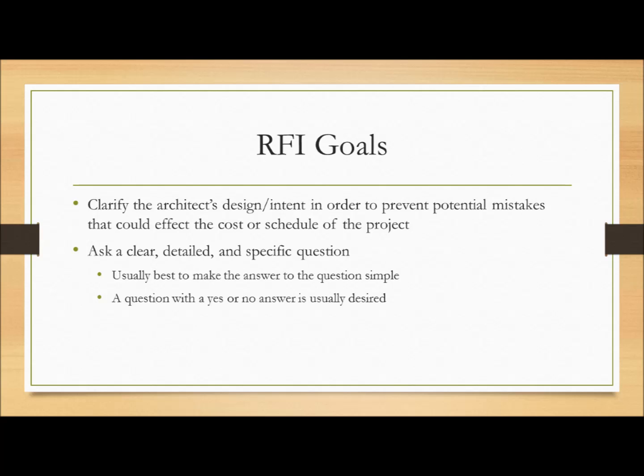The purpose for an RFI is to clarify the architect's design or intent in order to prevent potential mistakes that could affect the cost or schedule of the project. Ask clear, detailed, and specific questions. Usually best to make the answer to the question simple. A question with a yes or no answer is usually desired.